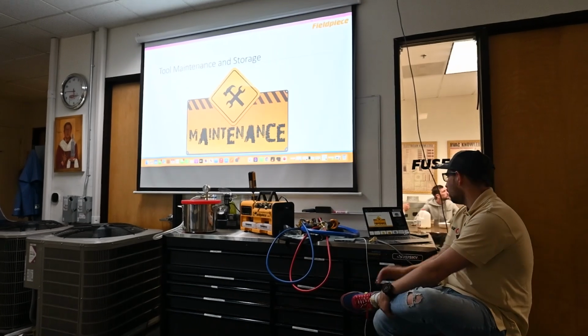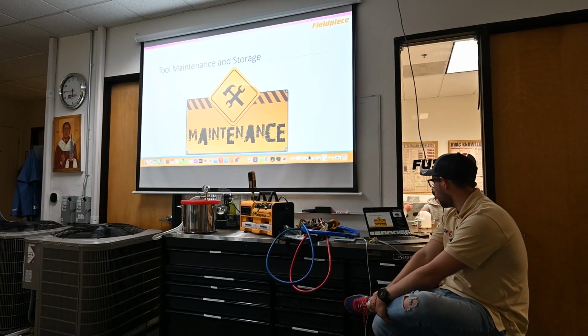Change the oil at the end of the job when the oil is warm and any particulate is likely to be in suspension. After the oil is changed, run the pump for 20-30 seconds with the caps in place so the oil in the actual pump gets exchanged with the oil in the reservoir. Periodically do a physical inspection on the pump for damaged cord caps and repair or replace as necessary. Oil changes with a Fieldpiece vacuum pump are easy and virtually mess-free.